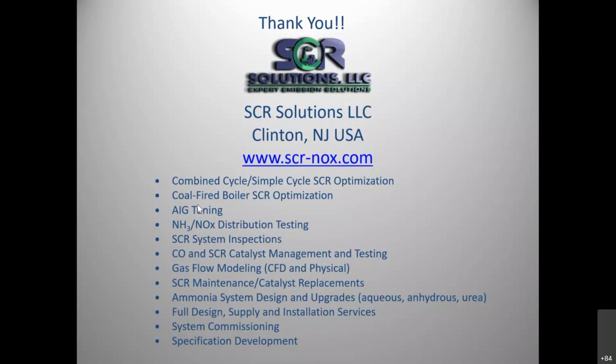The comment is for case study 1, where you state that the ammonium bisulfate in the back end tubes were cleaned every year, but the back pressure was going up even after they clean. I think it's because the CO2 ice blasting is effectively cleaning only the front few rows, like 1, 2, or 3 maximum, and the deeper bundles never get cleaned.